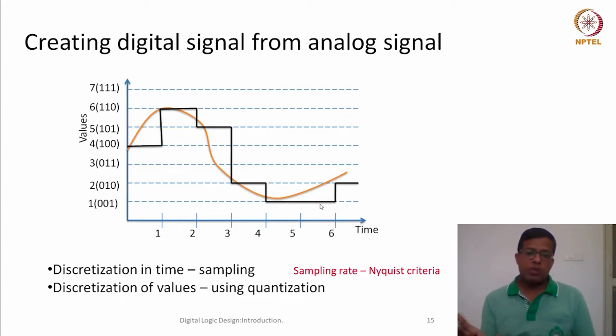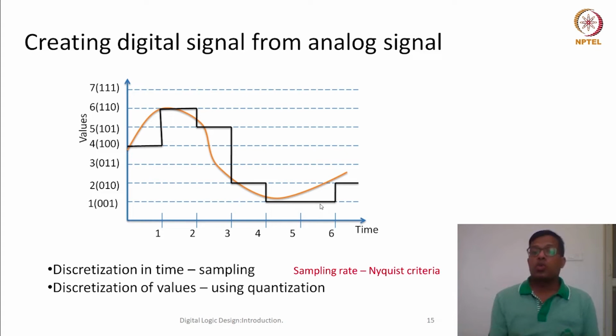It has been proved that if the maximum frequency of a signal is f, and it is sampled at 2f frequency, then we can always regenerate it without any loss of accuracy. So if our sampling rate is fast enough, we are sampling in such a way that all the minute differences are captured, then we would be able to reproduce that.